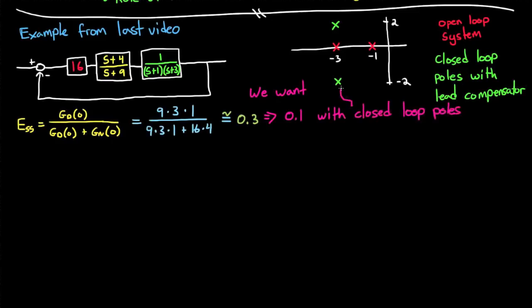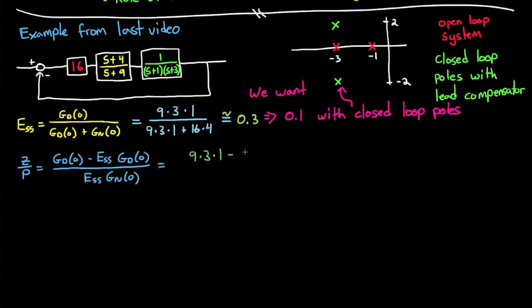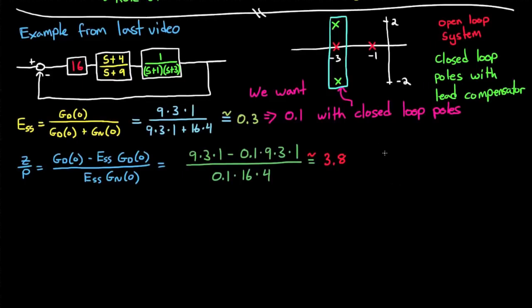But you need to keep the dominant poles where they are in order to meet your performance requirements to an impulse input. So you go through the process of designing a lag compensator, and you find that the zero to pole ratio needs to be around 3.8. And you know that the real portion of the closed-loop dominant pole is -3, since you designed it that way.